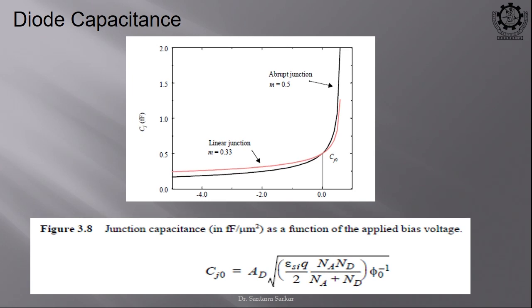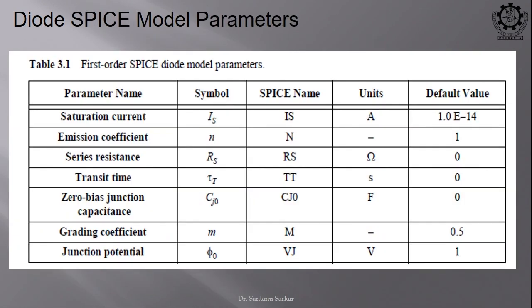So you can see that your Cj is now variable, and you can control it using a reverse bias potential, and design up to a certain value, so that at that particular value it is tuned to your circuit or your frequency. These are certain applications for this reverse bias capacitance. The same concept you can also use in the MOSFET.